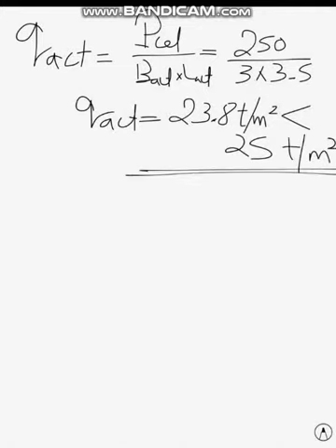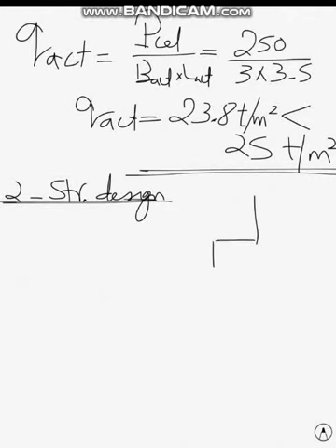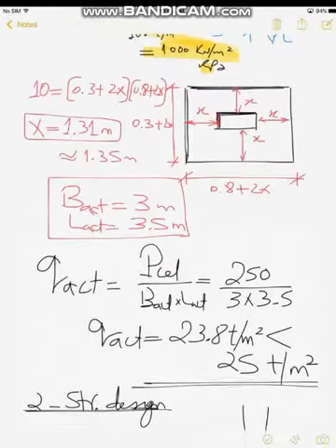So I finished the first step regarding the geometric design of the foundation. I have determined the dimensions to ensure the transmission of the load safely onto the underlying soil. Secondly, I need to determine the reinforcement and the thickness, and this is concerned with the structural design. In structural design, I have to deal with the foundation as a reinforced concrete member, for which I need to determine the straining actions. I will take a strip 1 meter wide,